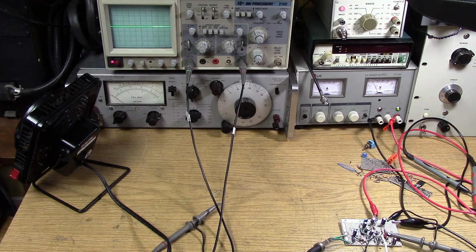So I want to add one more stage. We have plenty of these transistors that we're getting off the ATX power supplies. So I'm going to add one more stage with a gain of about 20. That's easy to do with an HFE-biased transistor, something between 20 and 25 dB of gain. That will allow us to run the lower level stages in the 50 to 100 millivolt region rather than way up at full gain.